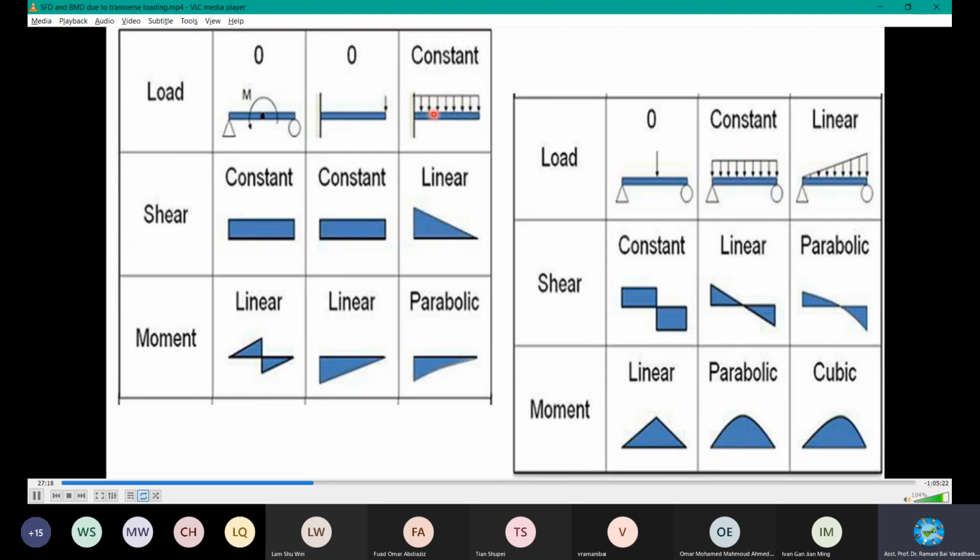Because it's a little bit away, but there is some loading. You see the curve, this one is a straight line, but this is parabolic. The moment distribution diagram is always parabolic for a UDL. It's not an inclined line, it's parabolic, because the response is gradually reducing, not at a constant rate.